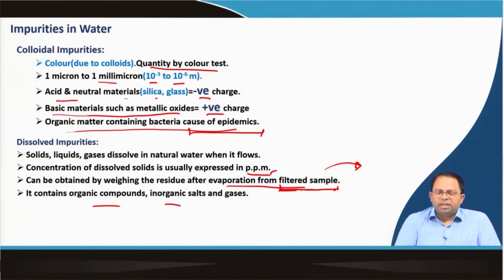If we do chemical coagulation, sedimentation and filtration, and then do this kind of evaporation, we are left with only the dissolved impurities, right. All the other impurities are already taken care of earlier. Or we can just do evaporation and get rid of the entire quantity of water that is there. All different kinds of impurities could be removed.